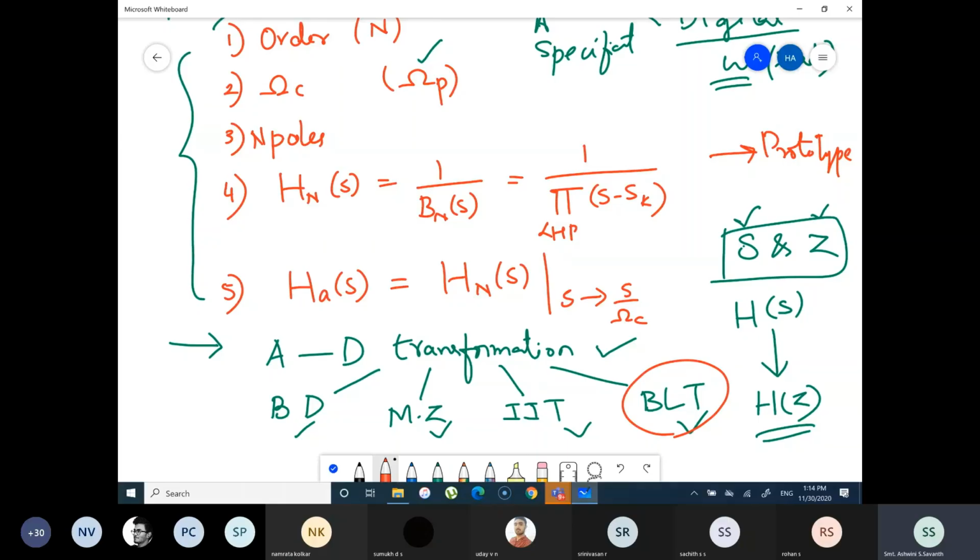So far what we have seen is only the analog IIR filter design. Now we'll have to learn this bilinear transformation to convert the analog filter to the digital filter. So once you learn this transformation, you will also know, when a problem is given to you, what specifications you have to take. Okay, design that filter and then convert it to digital. It's a little roundabout, we can say. That's how it is. So first, let's take up the bilinear transformation.